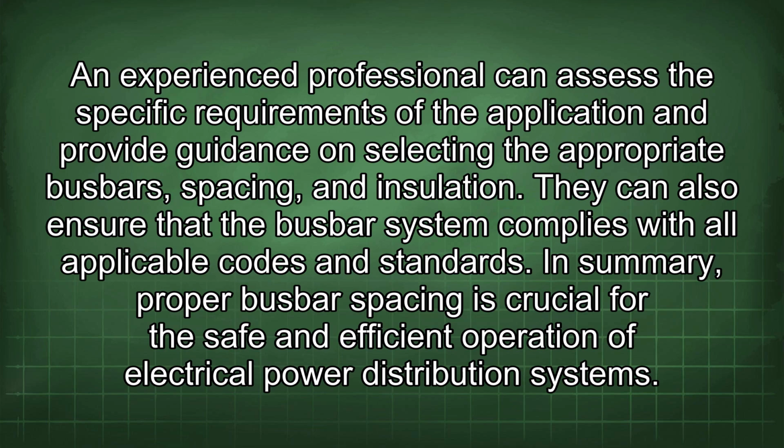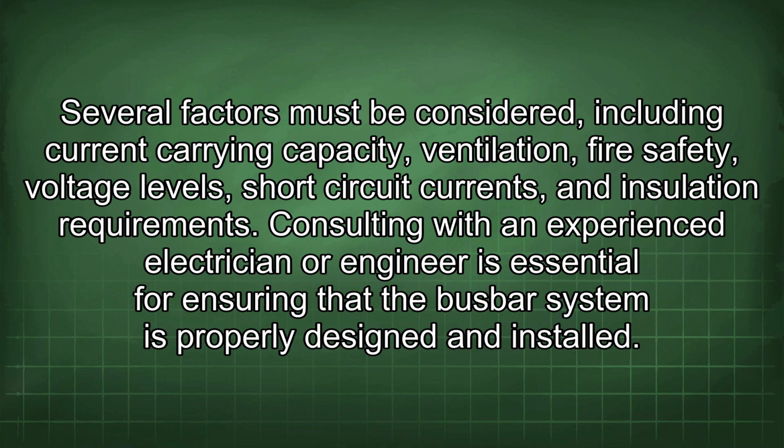In summary, proper busbar spacing is crucial for the safe and efficient operation of electrical power distribution systems. Several factors must be considered, including current carrying capacity, ventilation, fire safety, voltage levels, short-circuit currents, and insulation requirements. Consulting with an experienced electrician or engineer is essential for ensuring that the busbar system is properly designed and installed.